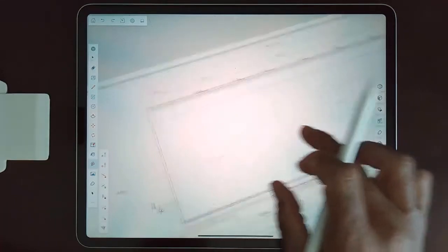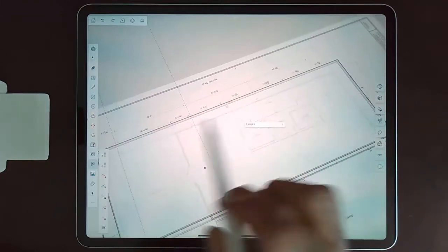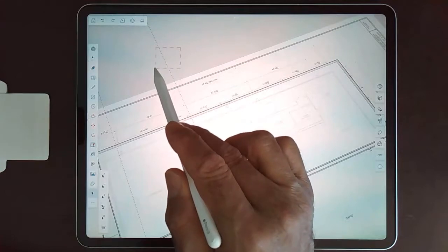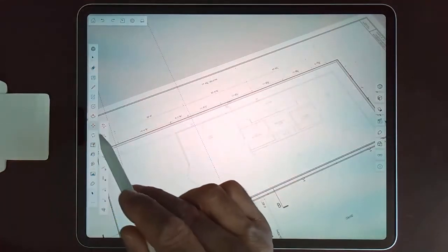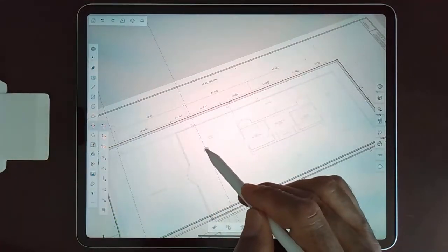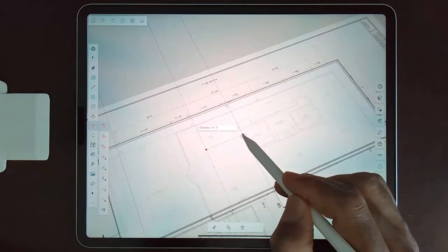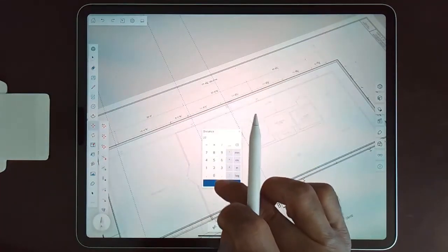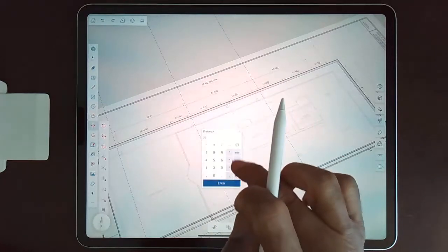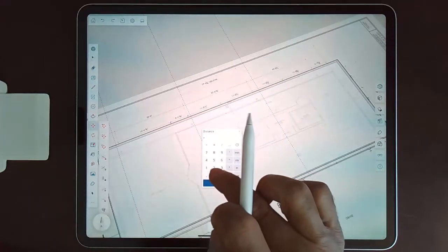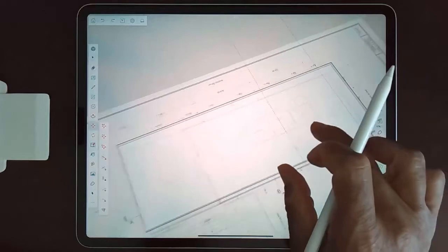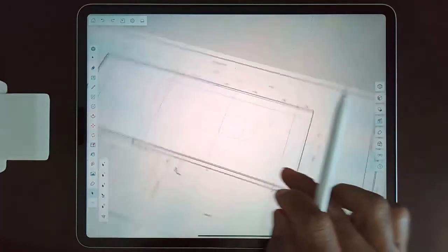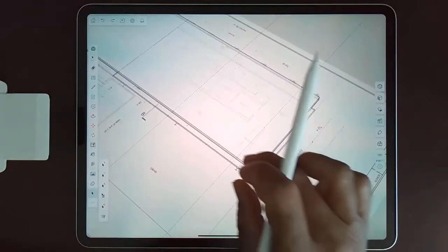And then we're going to take a quick shortcut here: make a selection of that guideline and use the move tool in copy mode to copy it over 22 feet. And having done that, you can now follow it up with a ×2, and that makes a copy of it. So now you have the 4 grid lines there, equally spaced at 22 feet.